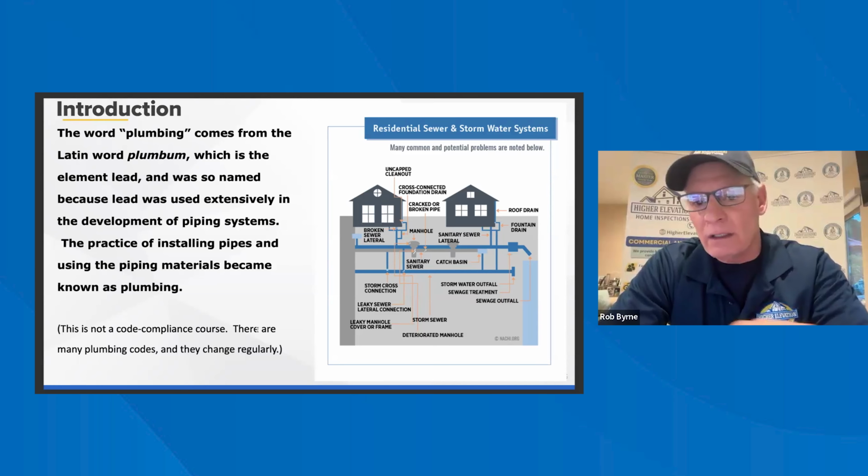Just to reiterate what Jim was talking about, when you're in a bathroom, you're running the multiple fixtures, you're checking to see if you get a temperature drop, a flow drop. And don't forget, if you have a 2-story house, the second floor would be even less pressure than the first floor. If you're having an issue downstairs on the first floor and you're losing water pressure, go upstairs and try to turn it on upstairs. Sometimes it doesn't even come through. So you could document that and visually show it to your clients. They'll understand it pretty easily.